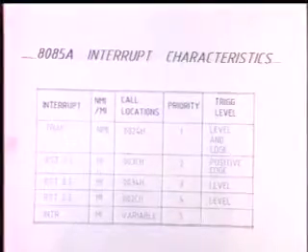Then the last one is INTR, where I have said variable. And here there is a certain catch. If I say variable, what does it indicate? First I said interrupt is external, so one has to provide a certain address. In case of TRAP and RSTs, the addresses are well defined, so it is a hardware vectored address, whereas in case of INTR, it is a software vector address.